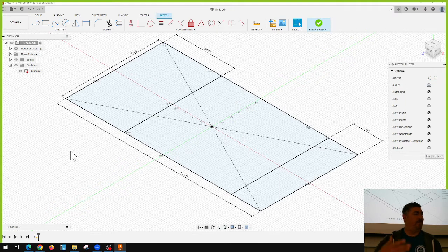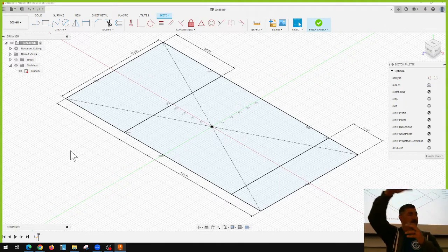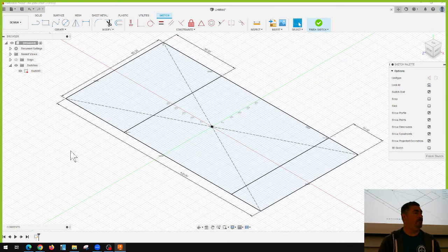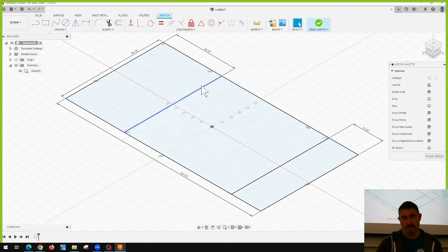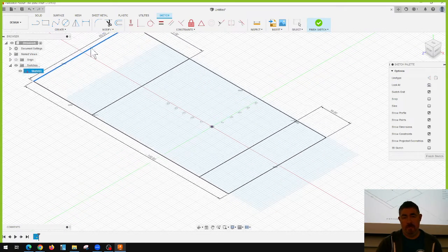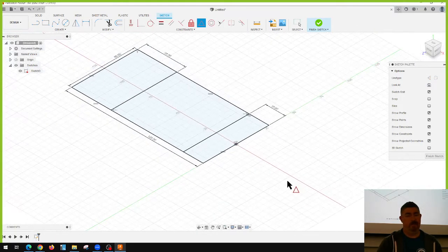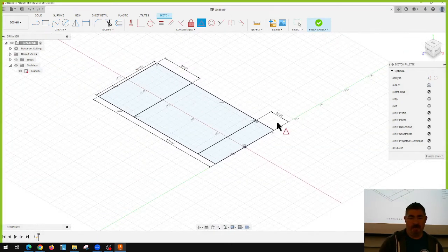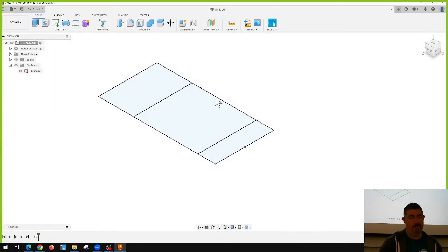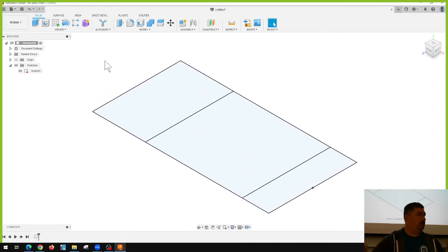So instead of going through and making the parts themselves, we're going to use this sketch to help lay out everything else. Okay? And actually for that, instead of making a center rectangle, I'm going to make it just like this front thing on the midpoint, just to get rid of some lines and stuff. All right, so I have this there. I'm going to finish it. So now I know my basic outline of the trailer.